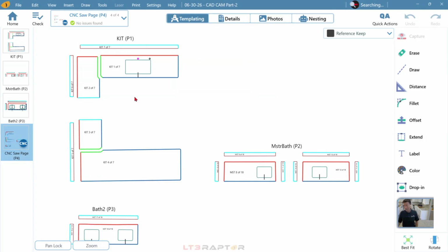Something else, I find it's quick to just do it right here. Some people like to wait till kind of the end. Because I want to end up sending this to a router, and typically in North America, we'll finish tops on routers, finish side down. We do have some folks that are coming into the meeting that are either from Europe or Australia and New Zealand, and sometimes they'll machine drain boards in there, so they might finish face up, in which case you wouldn't mirror, right?